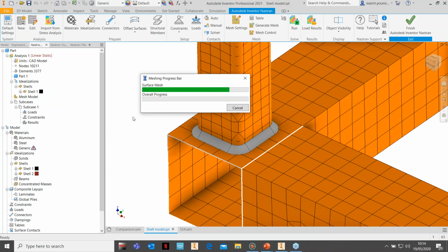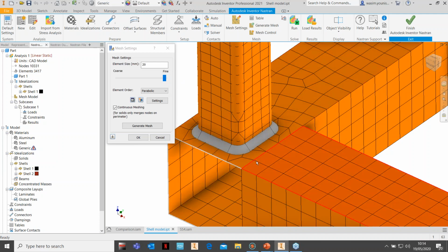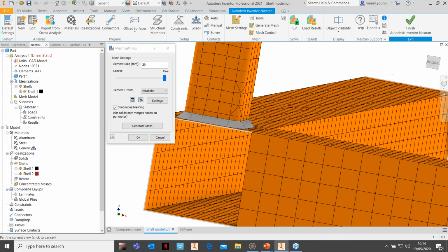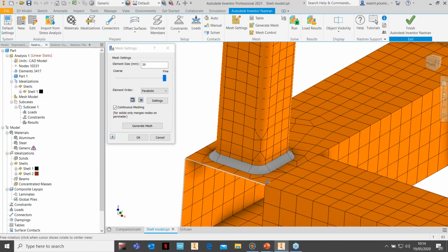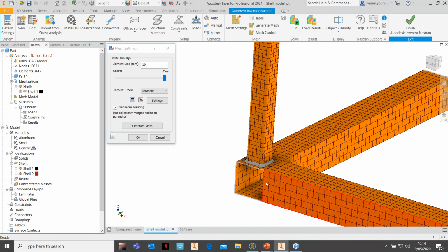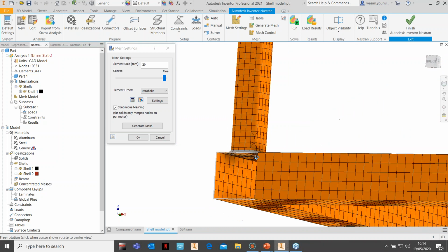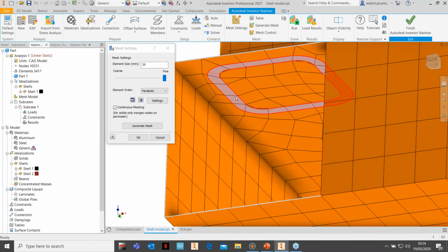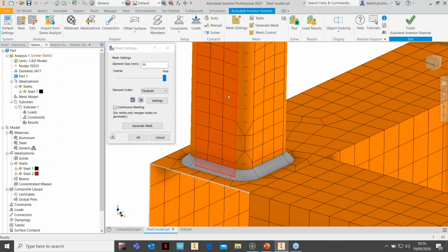what you'll notice is that it will merge the nodes of the surfaces. And obviously the mesh could be a little bit finer, and the only white lines now appearing are on the open edges. Now the only downside with this method is that I created that box section, the vertical one, which is touching the top face of the bottom box frame. So if I want to use this weld, I would have to create a gap between this box section and that one, so there is no contact between them, and then I can go and create a contact using this fillet here.